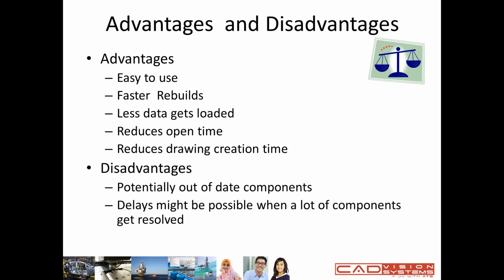About the disadvantage, there are potentially some out-of-date components. So you will see a red color feather, which means they are out of date, and also there may be some delay when there are a lot of components going from lightweight to resolved. So when you are changing thousands of lightweight components back to resolved, there will sometimes be a bit of lag, which takes some time to get resolved.